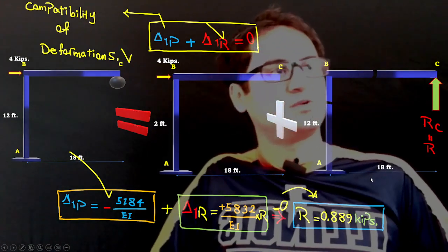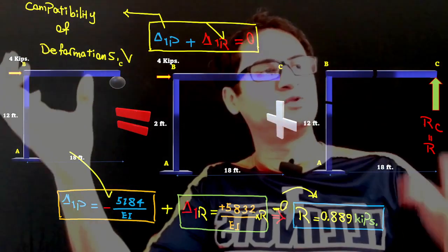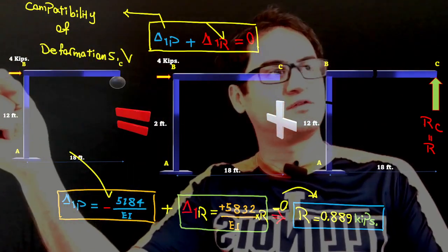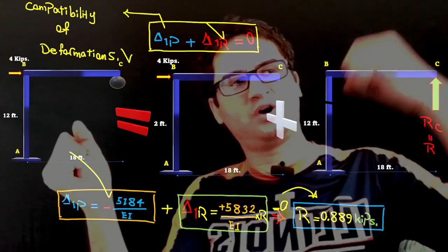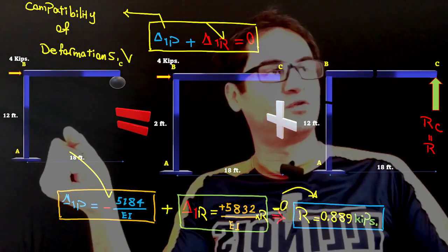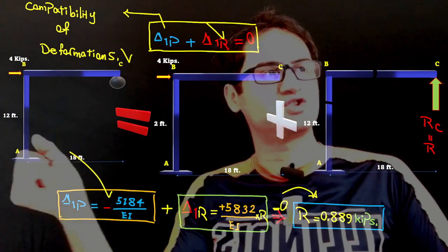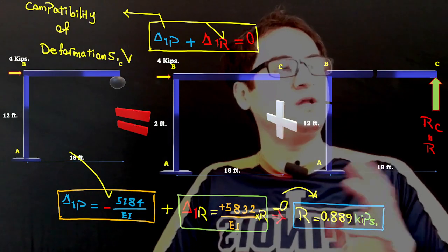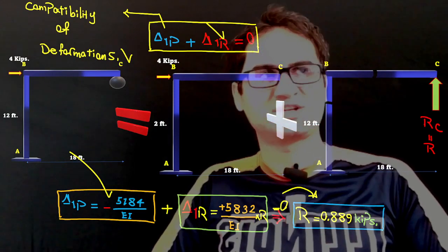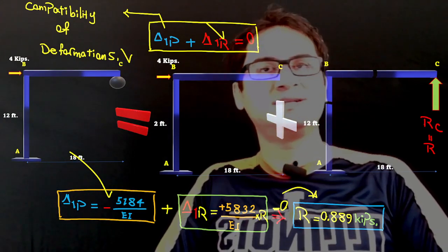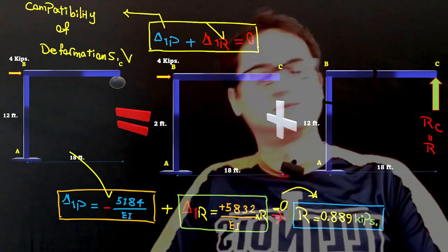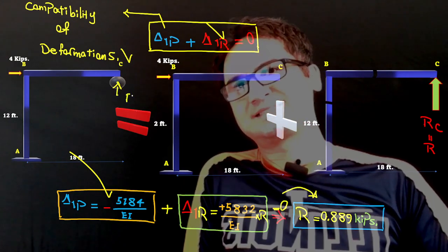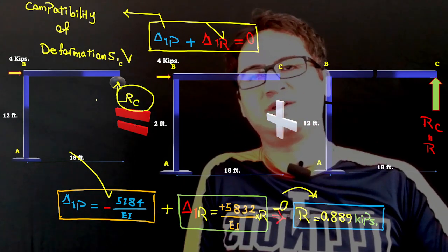That's all about how we can add up the two components for an indeterminate structure: get one delta 1 from the determinate structure, get the other one from the delta 1 for reaction for another determinate structure. By applying superposition, we can have both of them. The only unknown here is our redundant reaction. So that's our redundant reaction, which is the vertical reaction at C. We are looking for the vertical reaction at C.